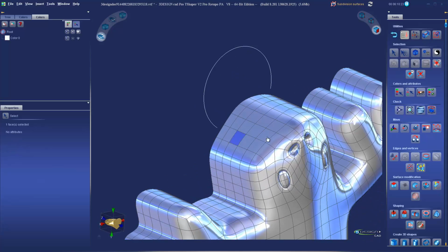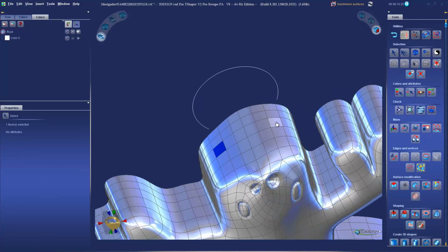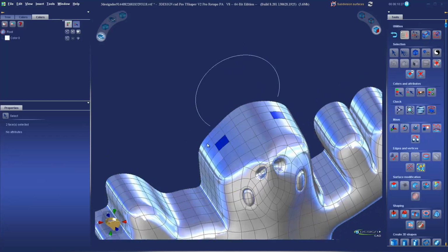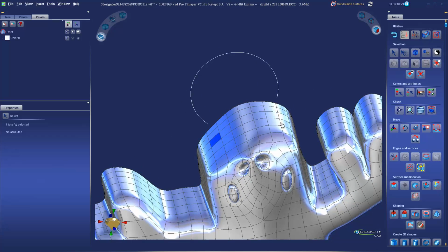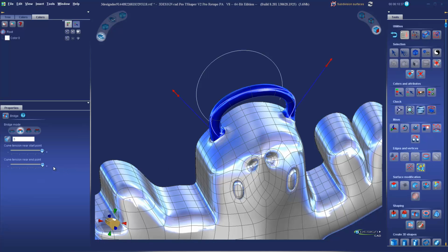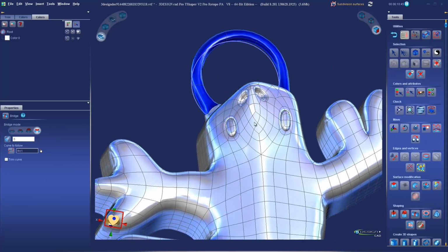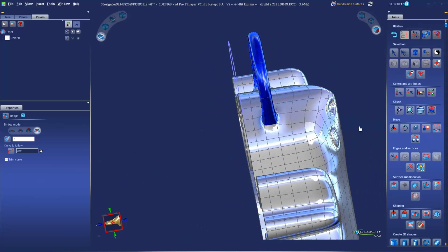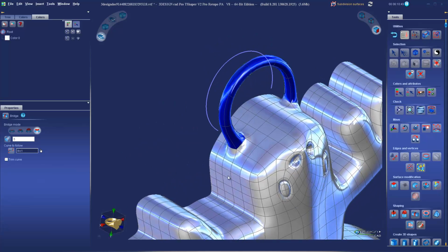And we're going to choose a couple of polygons. Thinking that one. Based on the curve, that looks like the closest ones. And then this time we'll do the bridge. And instead of using curved or straight, we're going to use a long curve and select that sketch curve that we drew. That way our bail is going to follow along precisely.